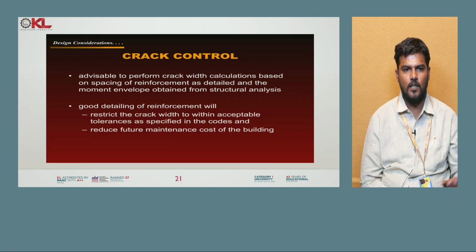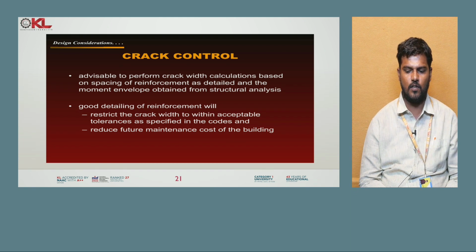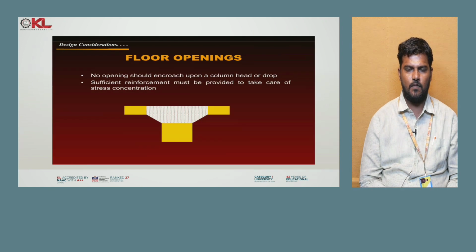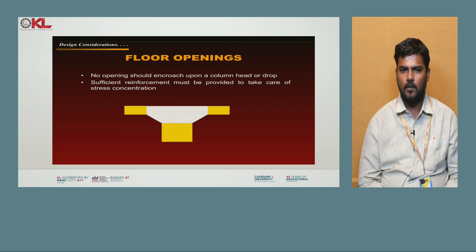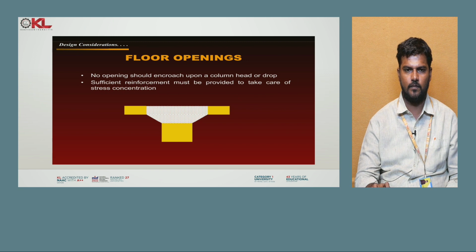Coming to crack control, it is advisable to perform crack width calculations based on the spacing of reinforcement as detailed and the moment envelope obtained from the structural analysis. Good detailing of reinforcement will restrict the crack width to within acceptable tolerances as specified in the codes, and it reduces further maintenance cost of the building. Coming to floor openings, no opening should encroach upon a column head or a drop. Sufficient reinforcement must be provided to take care of the stress concentration.